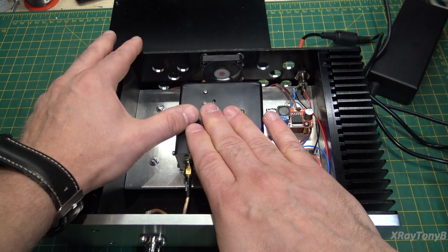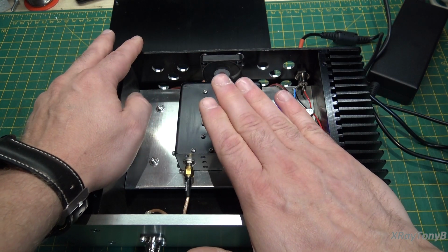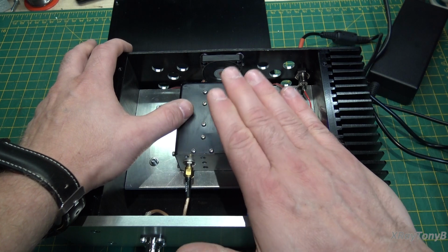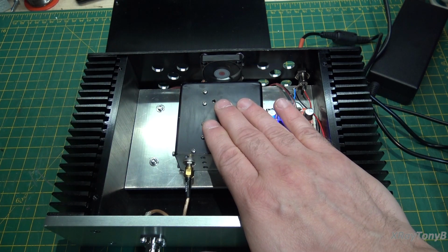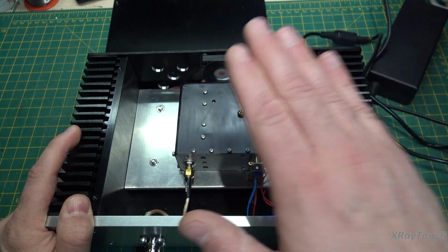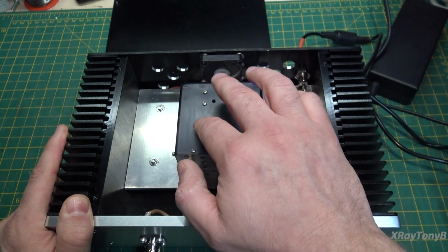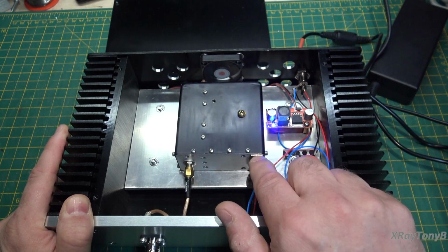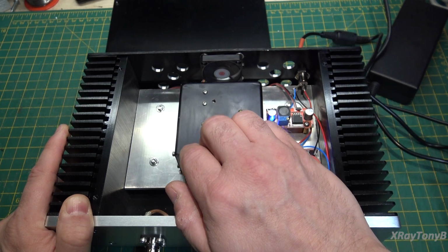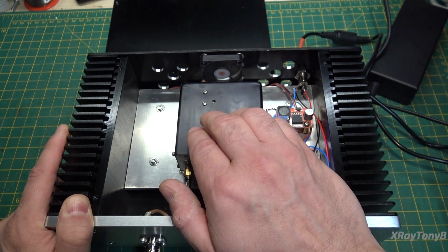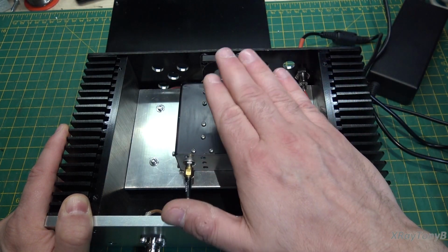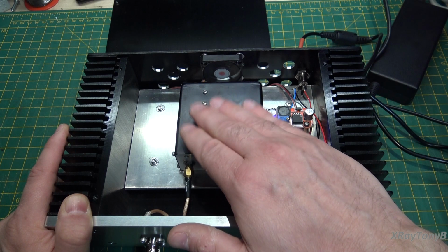This one here, the reason I purchased it is the individual who is selling these has the means to accurately calibrate them. He adjusts them to be exactly 10 megahertz, within a reasonable standard. He also rewires them to run off of a single 15 volt power supply. They come standard wired for split power supply, where you need a 15 volt and a 5 volt. Even though this thing has an internal 5 volt regulator, it's not used in the application that these come out of.